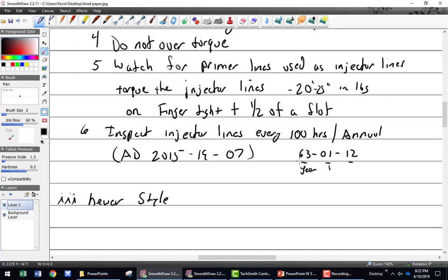where they are put, is really important. And so tie that in with 2-3 years ago, Lodi Airport, there's a Cessna Caravan with the Lotus skydivers that took off, and it crashed right after takeoff. Nobody got hurt, and that was a nice thing. It landed in a vineyard, and it flipped upside down, so it killed some grapes. But what had happened is they replaced a fuel line that had broken about 2 hours earlier. It was a very, very low time. And so the fuel line broke, so they replaced it.